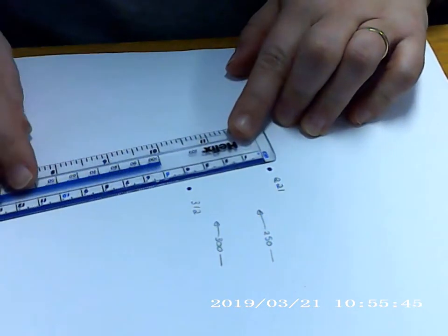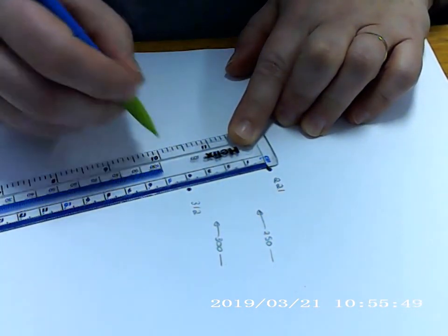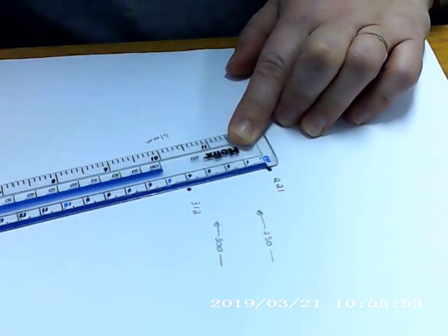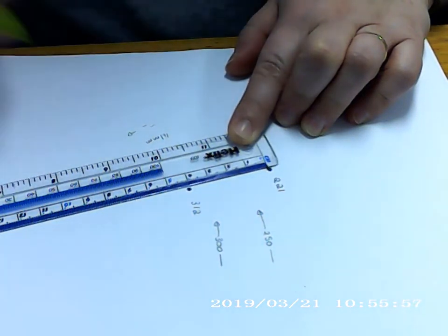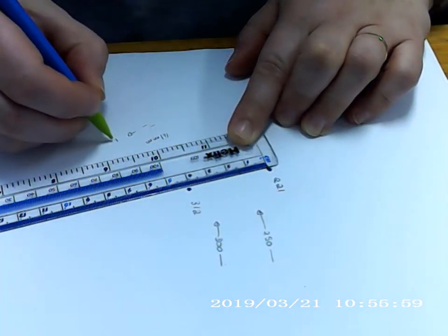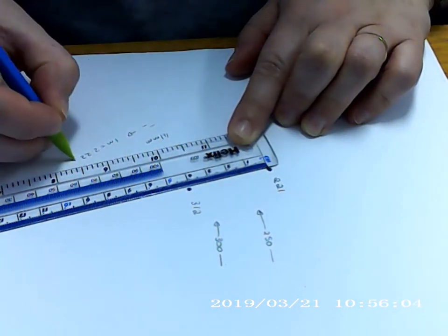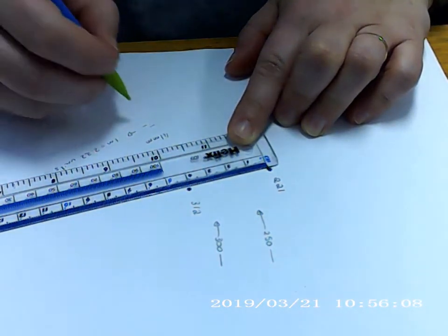Here I will demonstrate the various methods of placing contours between data points. To start with, we have 2 data points labelled 221 and 312 units, whatever the units are. We want to contour in 50 unit intervals, so we will need a 250 unit and a 300 unit contour in between these 2 points. To start with, we assume that the gradient of the data is constant between the 2 points.